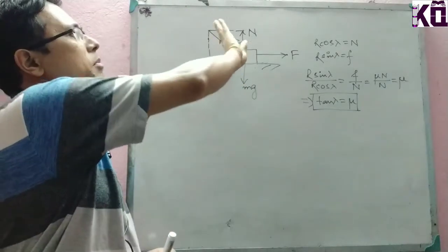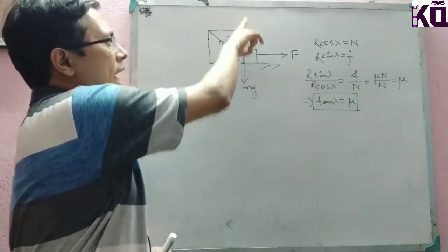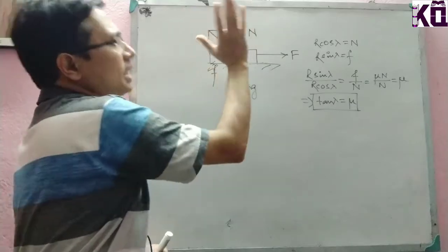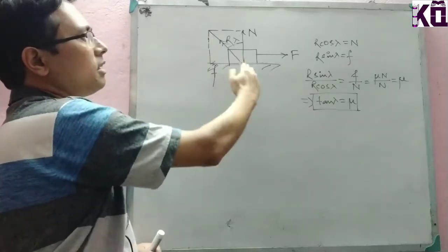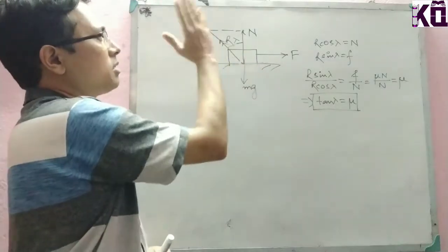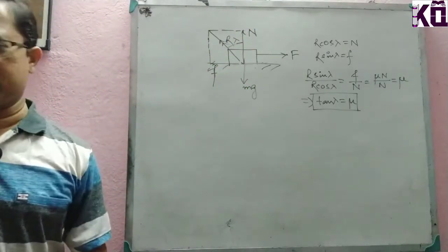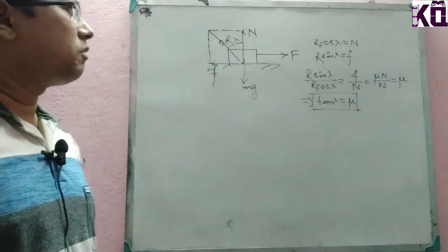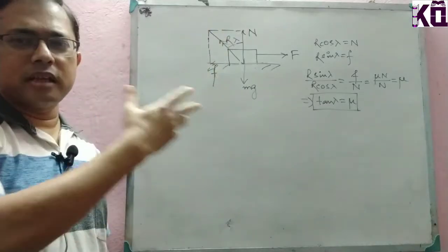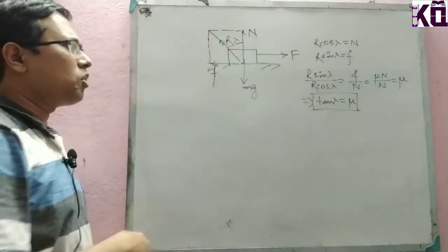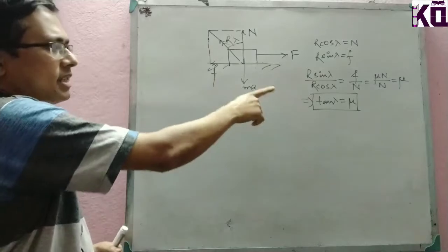If we rotate that angle lambda three-dimensionally about the axis, which is the normal reaction force, it forms a cone. This is the vertex, and this is the slant height of the cone. It is a hypothetical, virtual cone, and it has a special name, the cone of friction. The important part is tan lambda equals mu, and lambda is called the angle of friction.